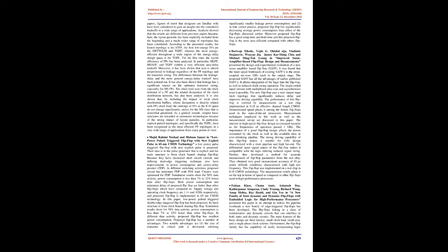The comparison has been performed in the whole energy delay area design space. The impact of layout parasitics has been included in the transistor-level design phase. The contribution of leakage has been considered in both standby and active mode, weighting it according to the logic depth in the active case. Wide loading and switching activity conditions have been explored, and other properties, e.g., the clock load, have been analyzed in detail. As opposed to previous papers, figures of merit that designers are familiar with have been considered to gain an insight into the considered trade-offs in a wide range of applications.